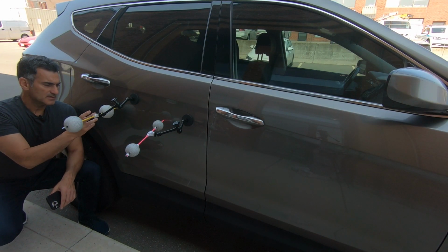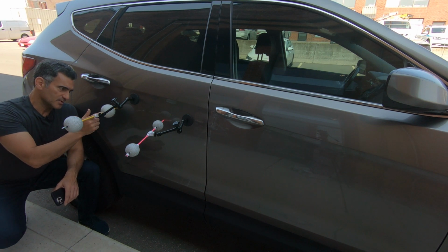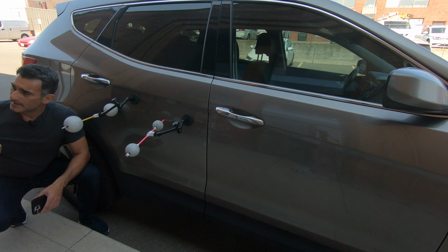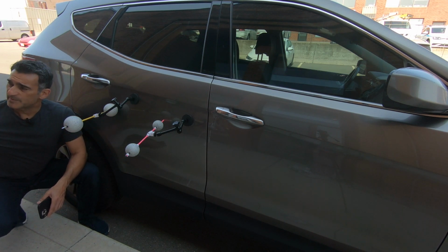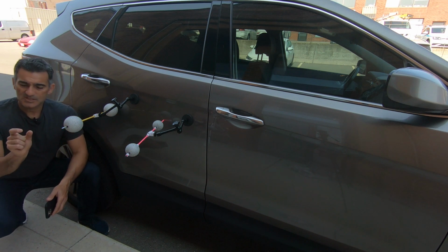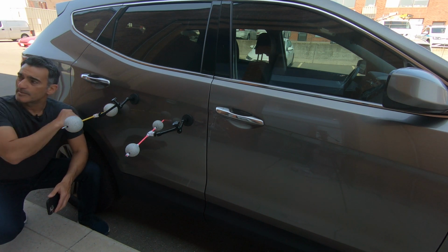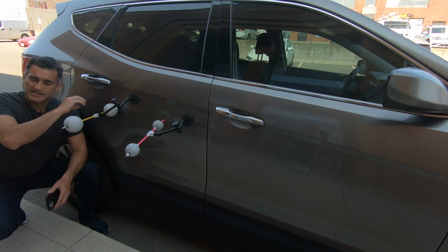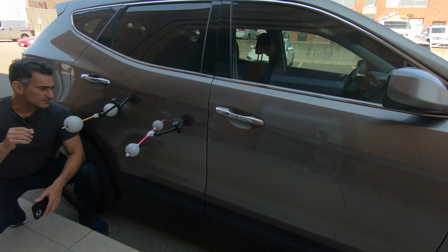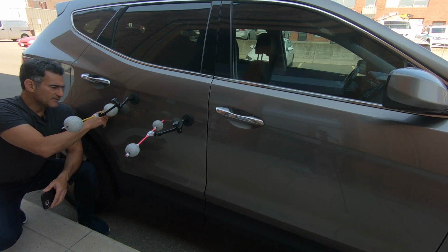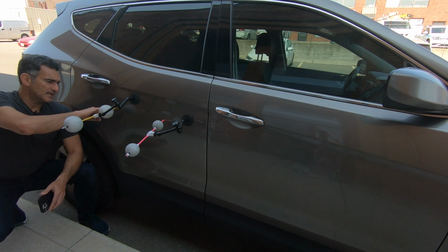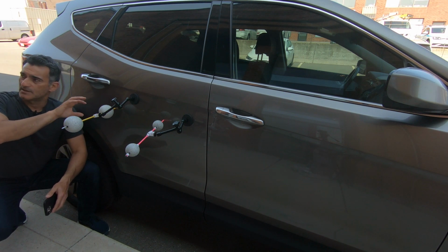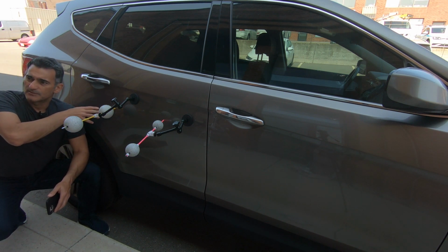Now the back one, because I want a wide separation, you would think that I would push this all the way to the back, so it's almost touching the car body, but that's actually not a good idea. The reason, just through experience and a lot of testing, is that the space between the sphere and the car body is so small that it has a very difficult time resolving the difference between the two, and you just get a mess in between. It looks like it's all one thing. So if you separate this by a few centimeters and leave a bit of space, you'll get a better resolve on the sphere itself. You get a more complete sphere and it doesn't blend in with the car body.